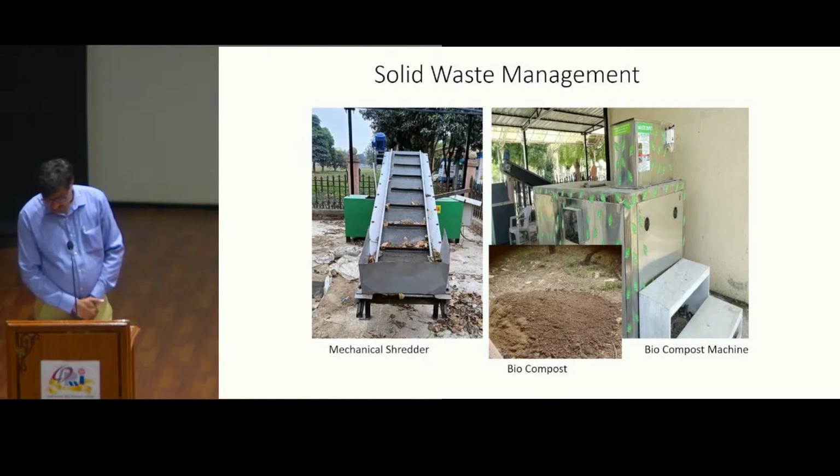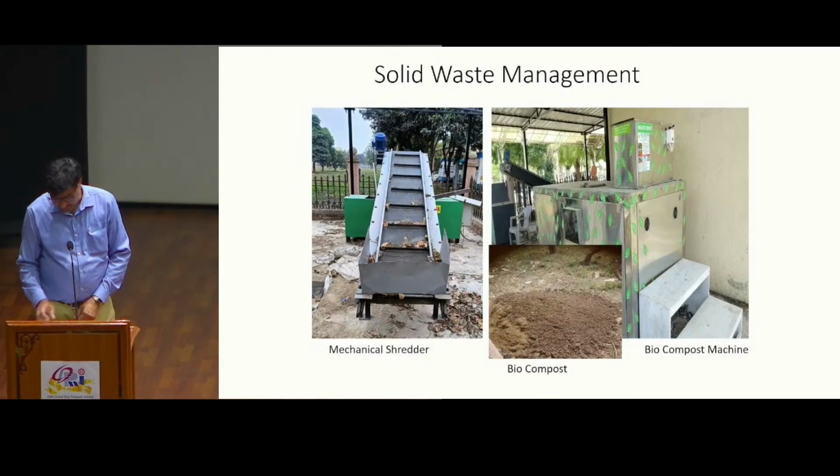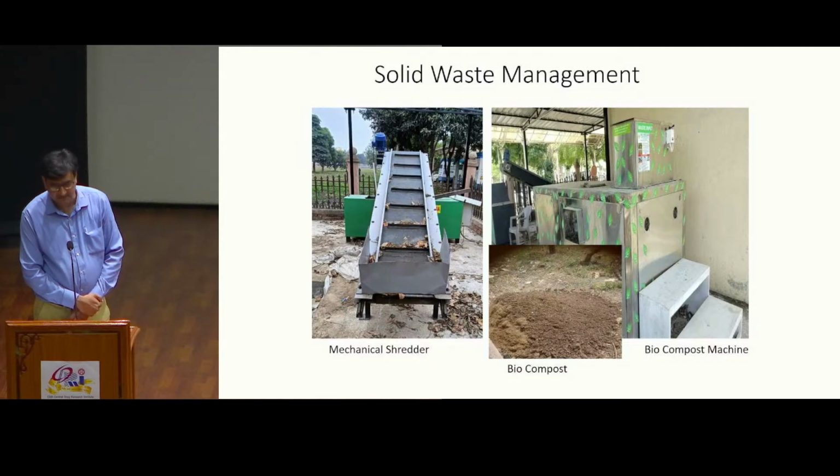Today, with the inspirational and motivational leadership of Director CDRI, we have added one more step toward the green campus. We have installed a 500 kg per day capacity biocompost plant on the occasion of World Environment Day celebrations. This plant will utilize all kitchen waste, leaves, grass and unused horticulture waste. This biocomposter technology is based on thermophilic treatment under aerobic conditions and homogeneous mixing, which converts the material to nutrient-rich bioorganic compost within a 24 to 48 hour cycle.